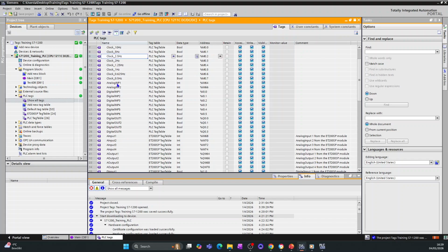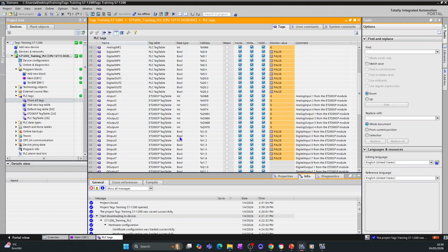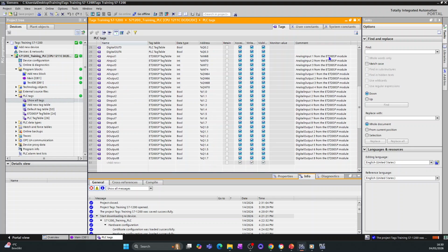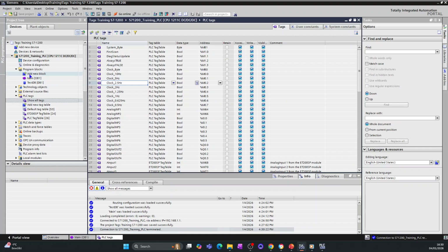We also have all our analog input, digital input. Currently, all our booleans are false, false, false. Our analogs are 0, 0, 0 because we don't have anything connected to those interfaces yet. Also on our ET200SP modules, we currently don't have anything showing up there, right? So this is what we have. Now I'll go offline. We will just quickly do a small program to test our simulation.